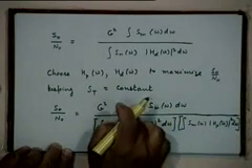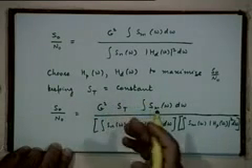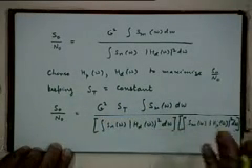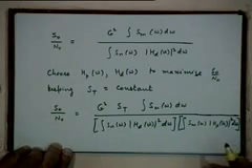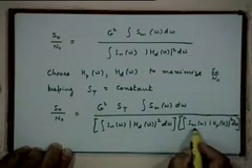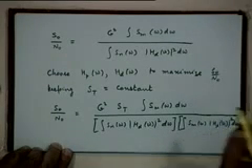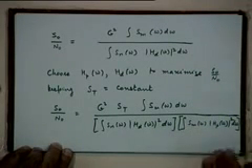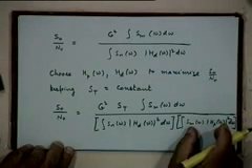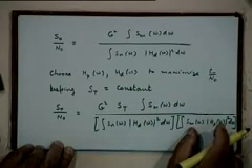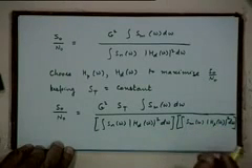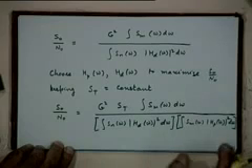This is nothing but St. The transmitted power is the power of the signal which is coming out of the pre-emphasis filter. The input of the pre-emphasis filter has a power spectral density function Sm omega, right? So the power spectral density at the output will be Sm omega times Hp omega mod square, and the area under the power spectral density at the output is the total power that you are transmitting, right? The power spectrum is given by this product, and the total power that is being transmitted is the area under this power spectral density. Is that okay?